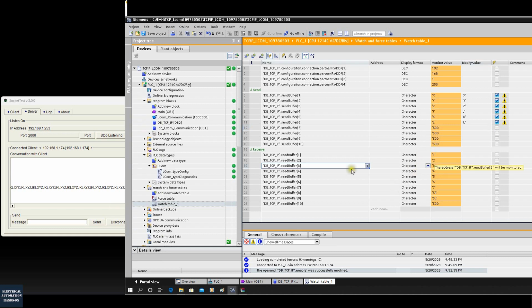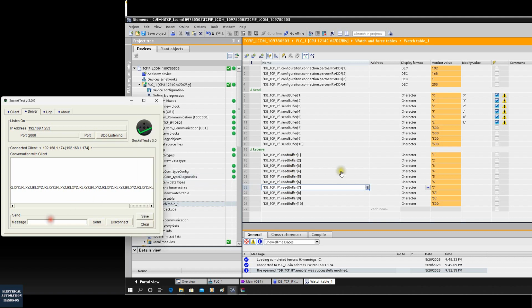And here's one great feature I like to show. The reading buffer. While we defined this reading buffer, we defined the maximum. That means it's a very huge buffer, very long. So basically it can receive anything we try to send. If we just send a bunch of data here, we can see it can receive. This receive length is dynamic.